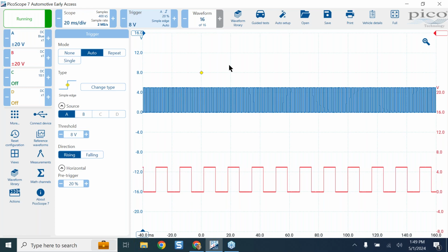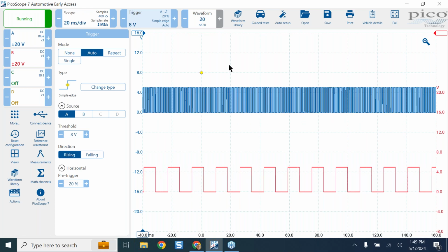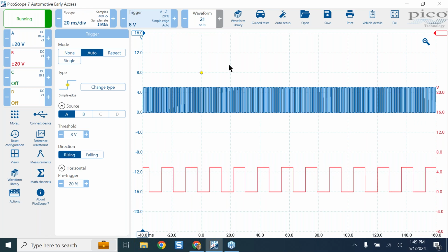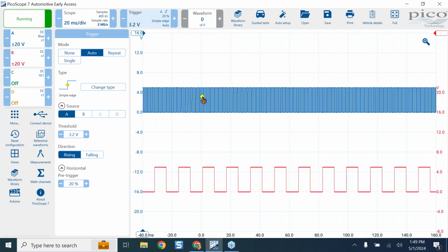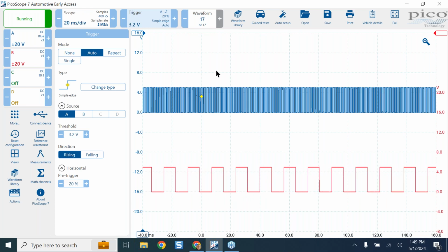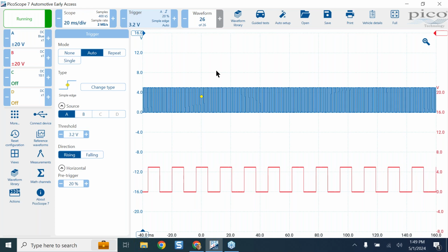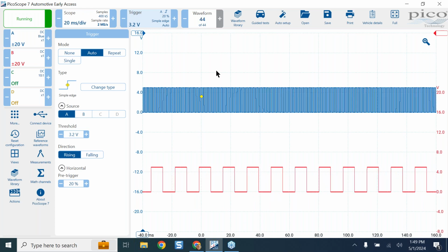And so it does look choppy, or it does look blocky, but it's giving you what you need. You have to just determine where you're going to set the trigger point. In this case, if we just lower it down, I'm going to drag and drop it. I'll lower it down, and it will stabilize my signal. It's just a digital, frequency modulated signal on the top.